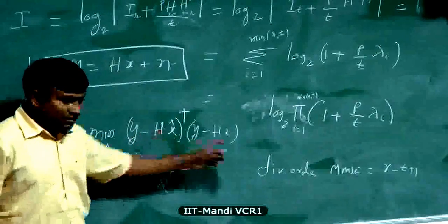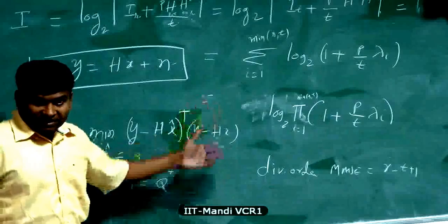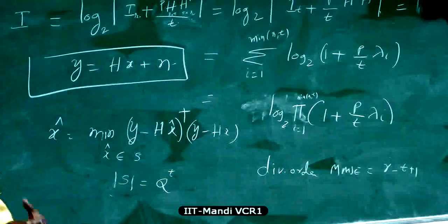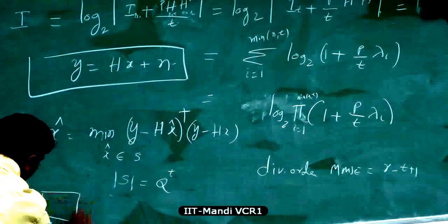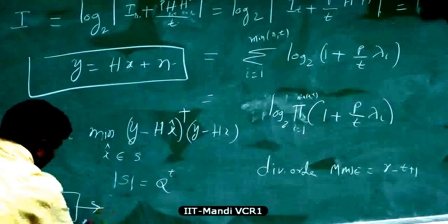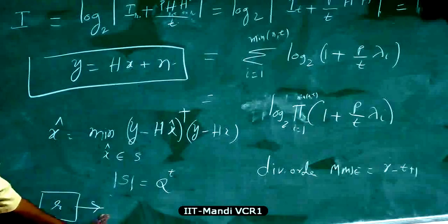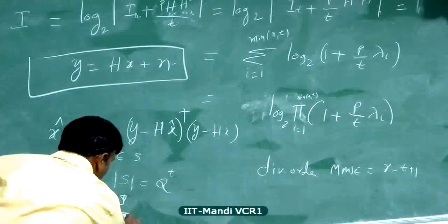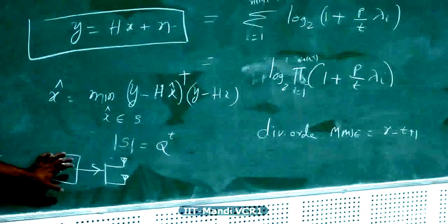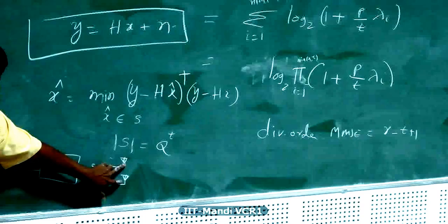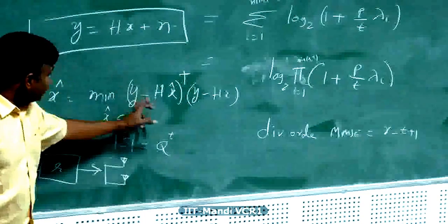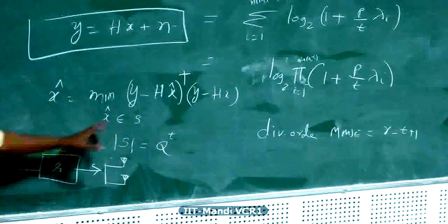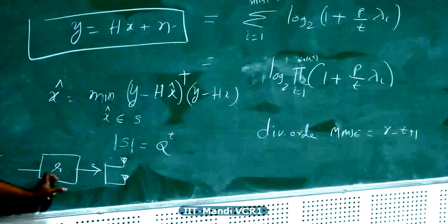I'm not saying it would approach that capacity, but if you bring coding into the picture, this is only a demodulation, right? And then you have to decode x1 and x2, the elements of x, using a channel decoder. You can either separately encode the elements of x, or you can jointly encode them. That is, there is a channel code of rate R, and then you can split the output symbols and transmit them on different antennas. It's like a single code. Transmit them on different antennas, decode using MMSE or MLD, demodulate, and then decode using a channel code.